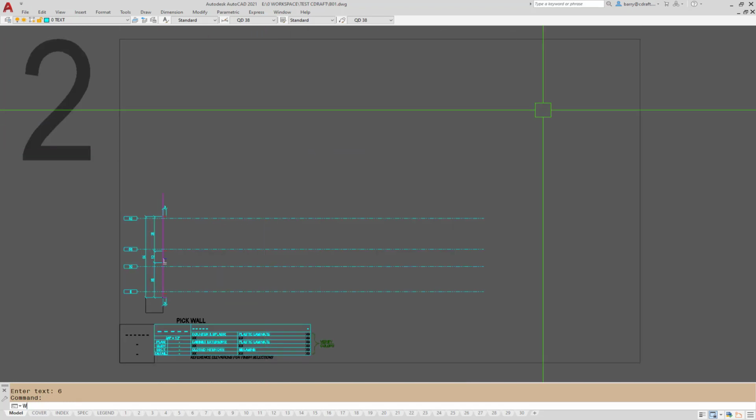And we'll do a W2. That's a wall cabinet, 2 doors. The width, let's go with 30 inches. We've already put the height in. We entered the height with our filler command, so we can spacebar through that option, and it asks how many shelves do we want. For this, we'll put in 2.